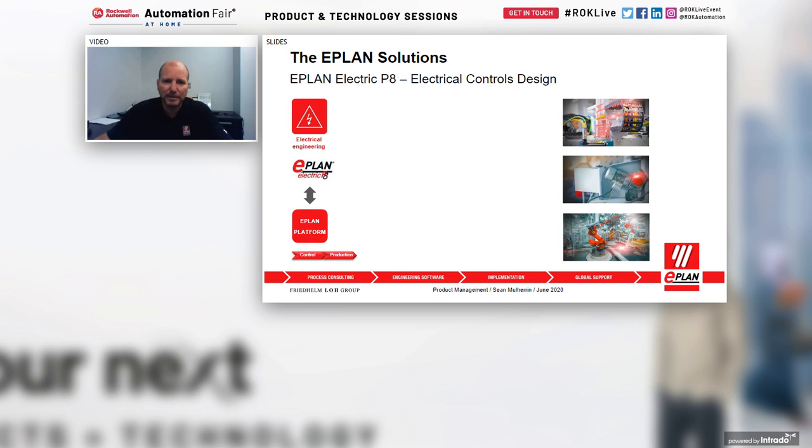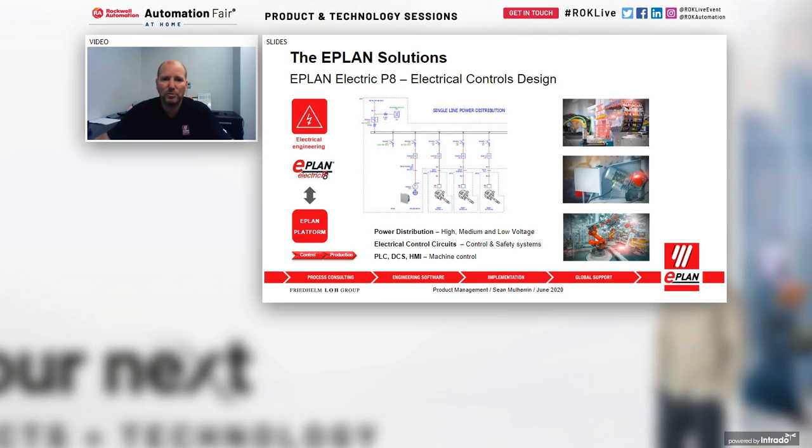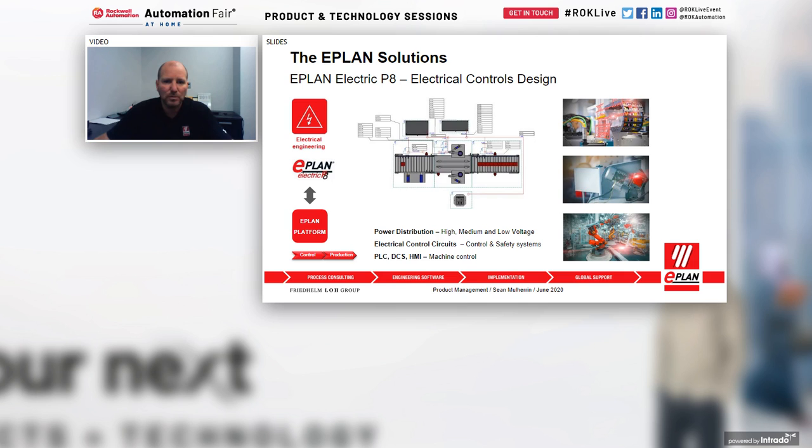EPLAN Electric P8 is your electrical controls design system. This allows you to design anything electrical, from single line diagrams for power distribution, so you can easily capture your components here in a single line environment. You can also lay out all of your cables. So if you identify all of your cable trays around the machine, you identify where your sensors and your actuators are, then you can route the cables and do cable length calculation in 2D. So this is a Fieldsys application to design or to lay out your cable topology, for example.